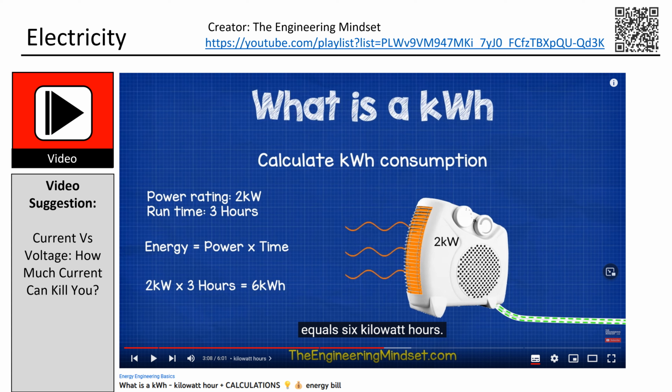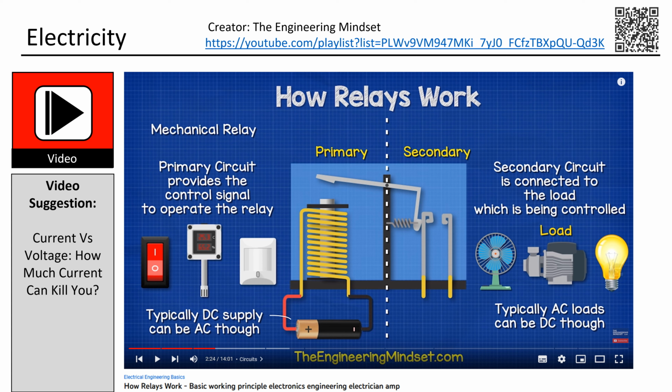Since you pay your kilowatt-hour consumption, you should be able to perform little calculations with it and know how to measure it. It is really not difficult. Since you will plug your system into 110 volt or 230 volt, and all my designs and many tech designs work with 12 volt, you should understand the concept of a relay. With that nice device you can control bigger circuits with just 12 volt low voltage circuits.